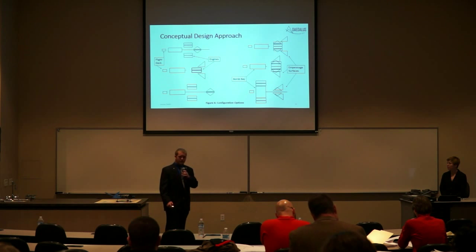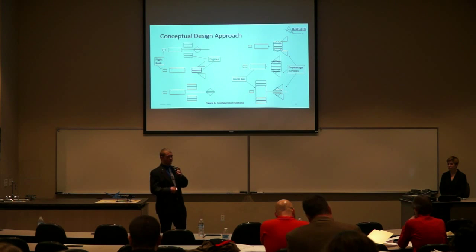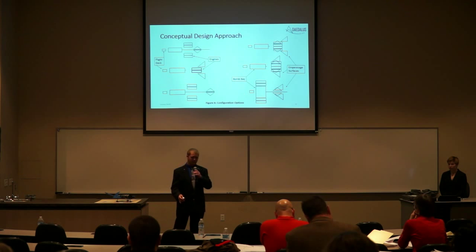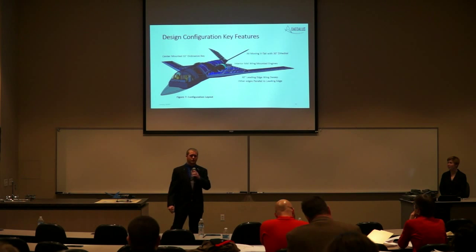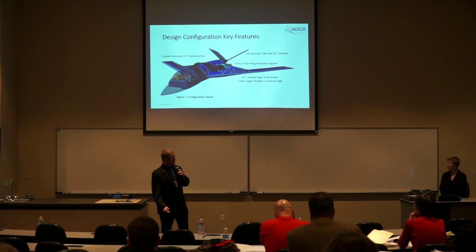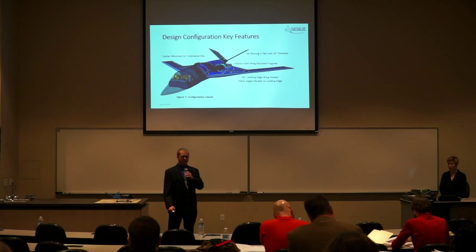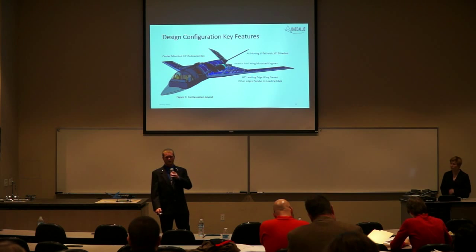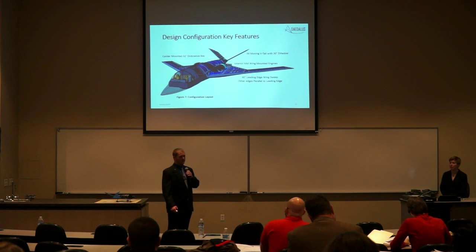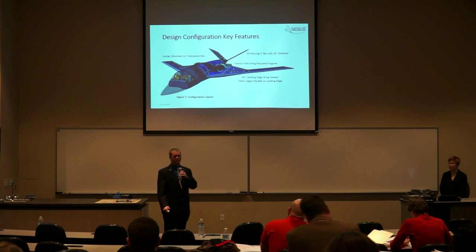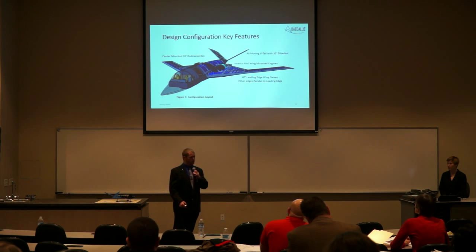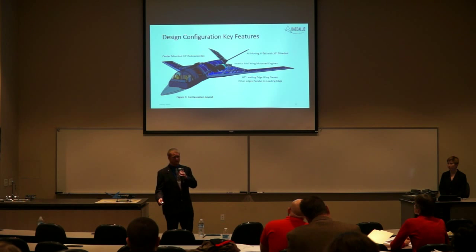Through a down selection process, we went from these six configurations down to four, then down to two, and finally to the final configuration shown behind me now. It has a 40-degree leading edge sweep, an all-moving V-tail with a 30-degree dihedral and 40-degree sweep to match that leading edge, a center-mounted 32-foot reconfigurable bomb bay, and interior-mounted medium bypass turbofan engines. Again, the reason for choosing those engines will be discussed a little later.